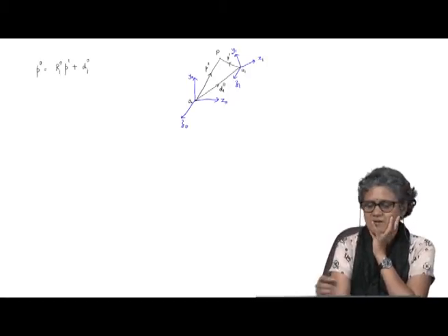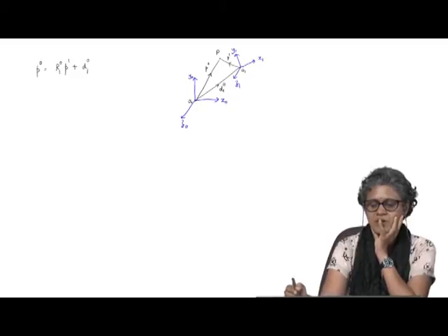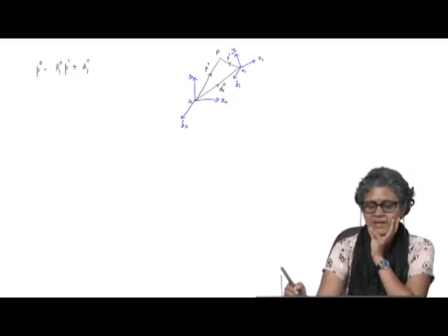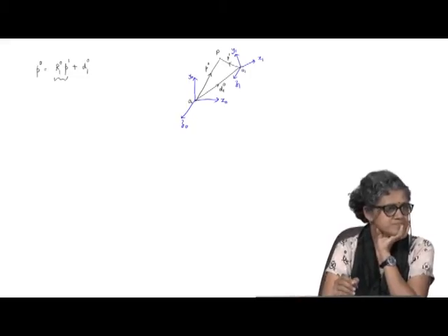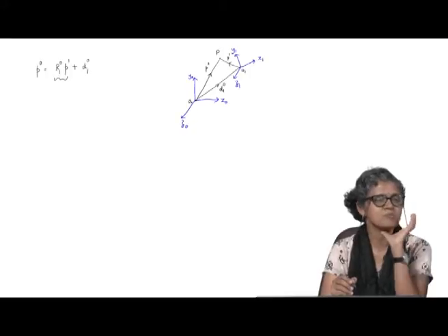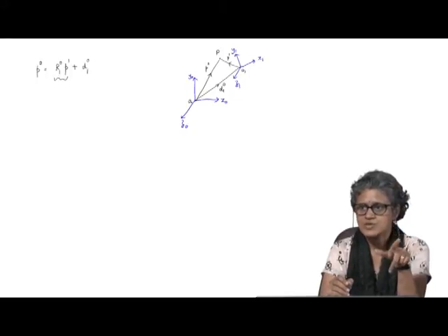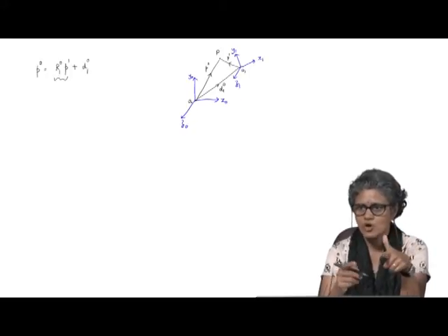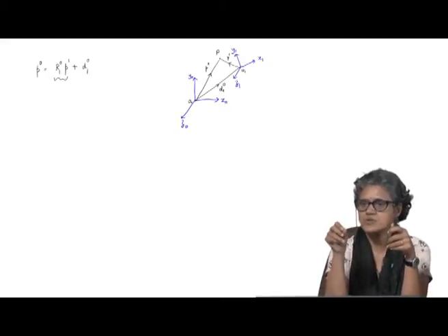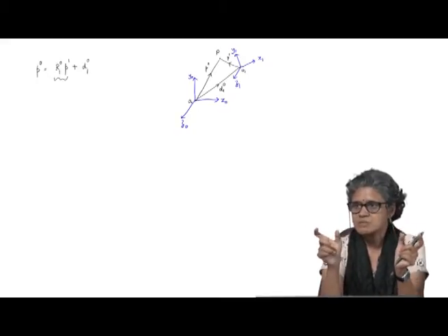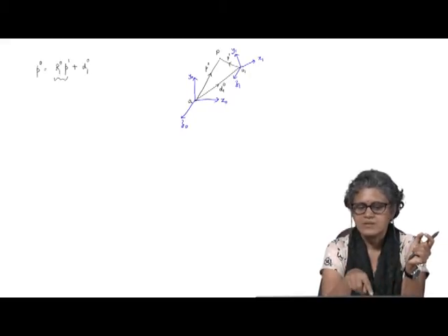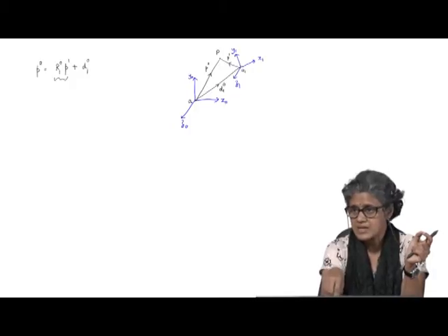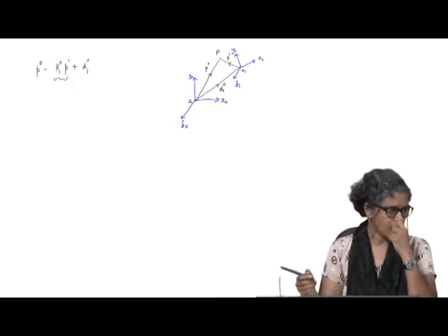So, this vector transformed into a coordinate system that is parallel to x0, y0, z0 would be this term here. You multiply it by the rotation matrix, because we saw in the previous case when the origins were coincident that those two representations are equal. So, I have converted everything into this base coordinate system before I can add these vectors. Okay.